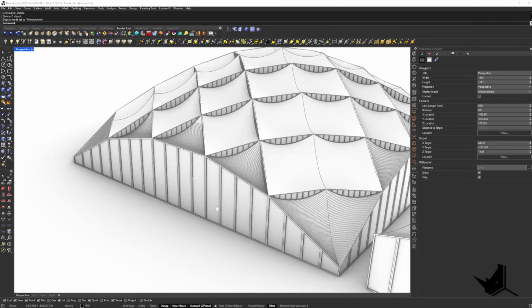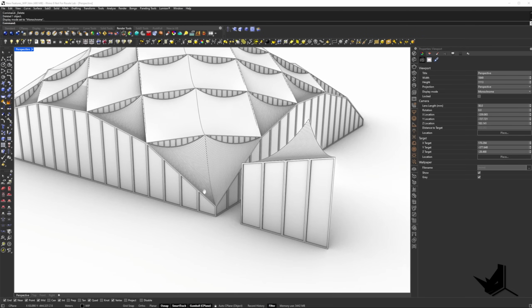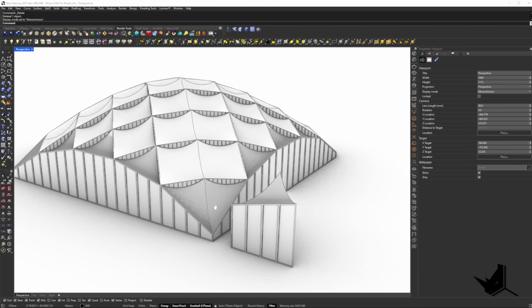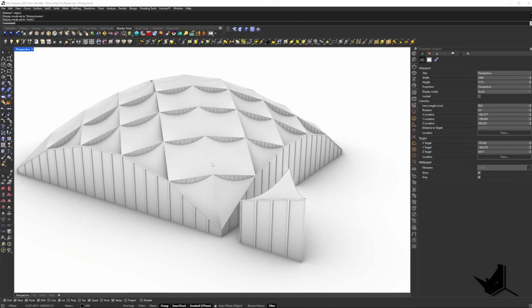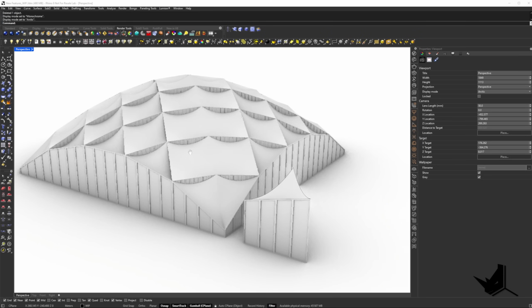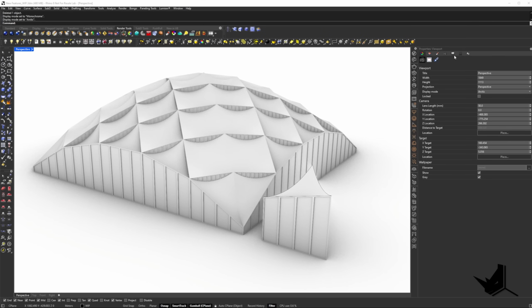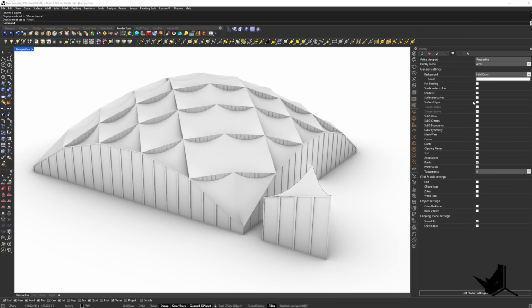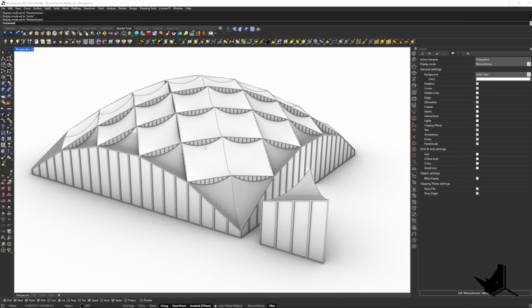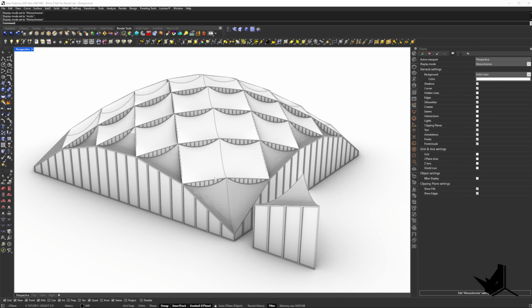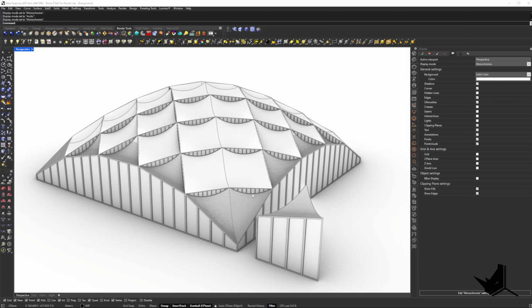So you may be wondering what's the difference between this view and the regular Arctic view. So let me show you. When you click on the Arctic, you're gonna see that it's gonna be a little bit washed out. And of course you can play with the Arctic mode itself, and you can try to get it as close as you can to the original, but I found Monochrome is really solid out of the box, and it's gonna give you the best result if you simply want to export your view from Rhino for architectural diagrams.